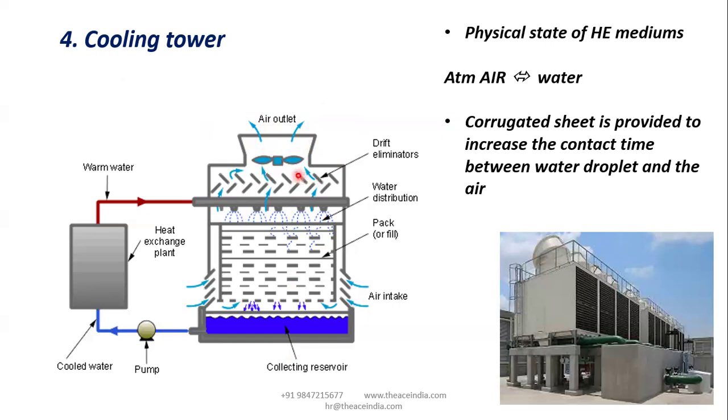We know, guys, we've been spraying the water right inside the cooling tower itself. So there might be a chance of water droplets escaping alongside the hot air, isn't it? So in order to maintain the water level inside the cooling tower, it is fairly packed with drift eliminators.